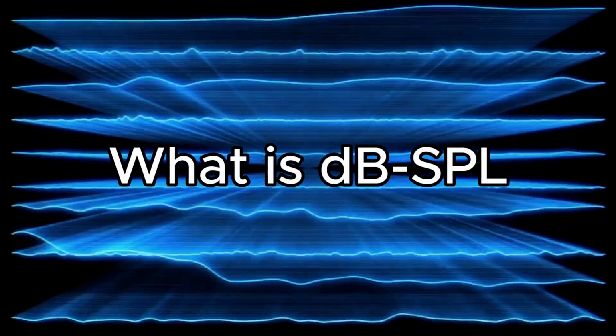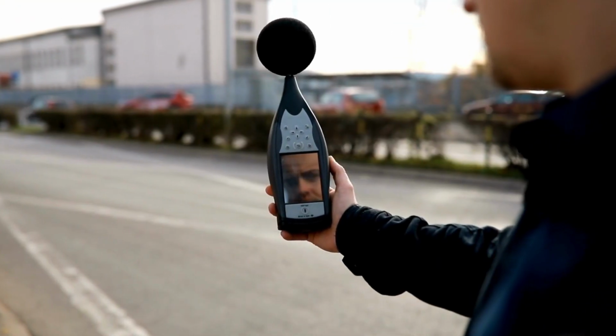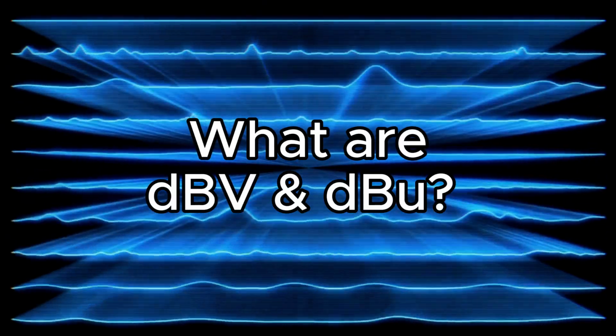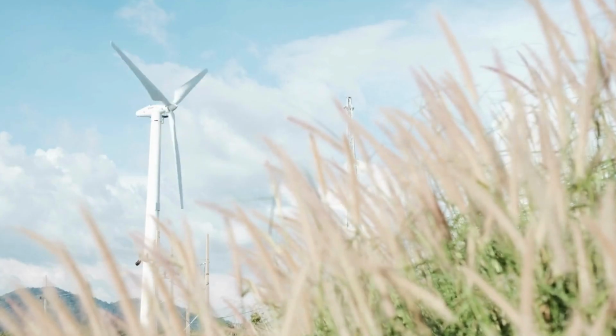So what is dB SPL? It's the way we measure variations in air pressure caused by sound waves. Next, we're going to be talking about dBV or dBu. The V in dBV stands for voltage. That's right, we just went from air pressure to electricity.